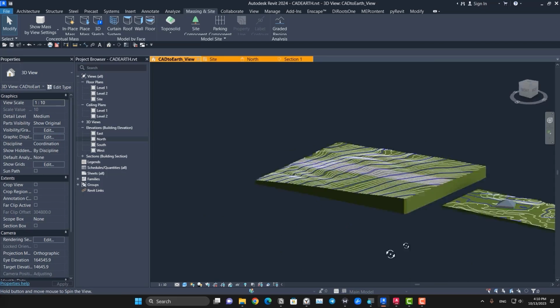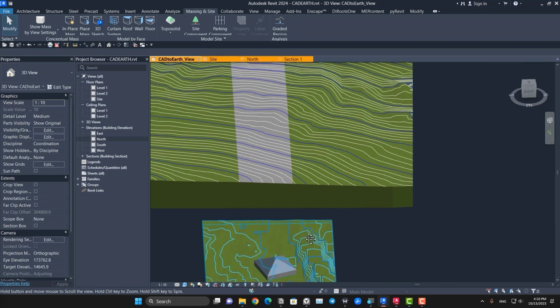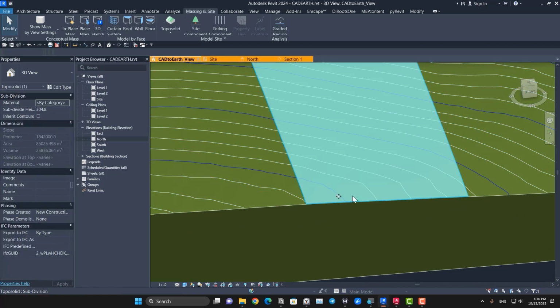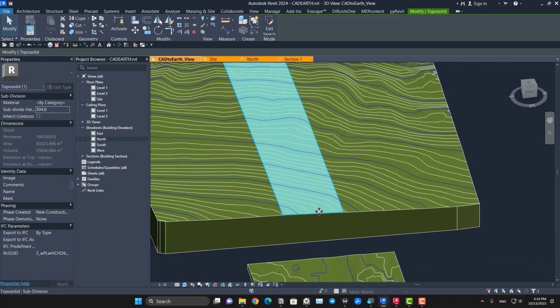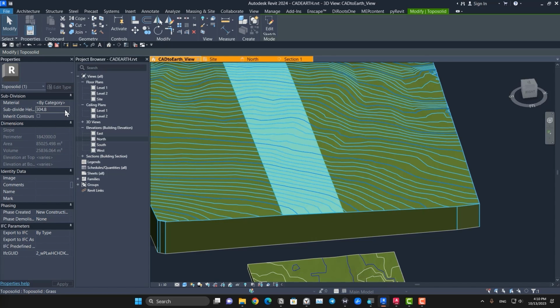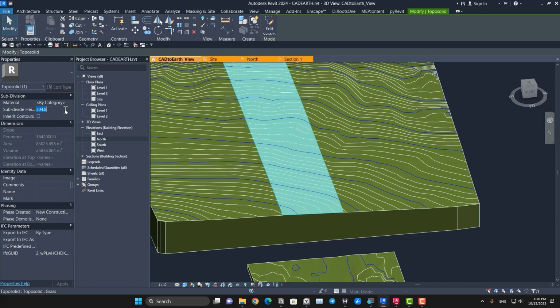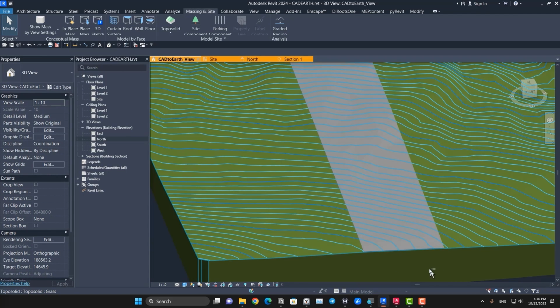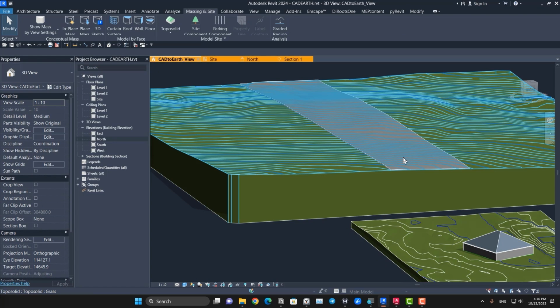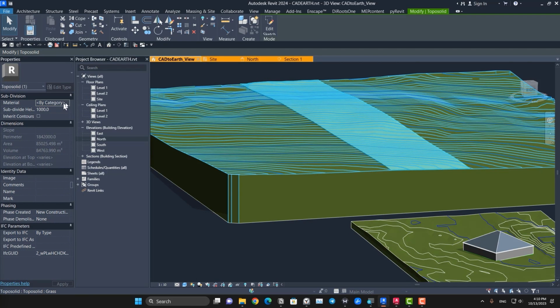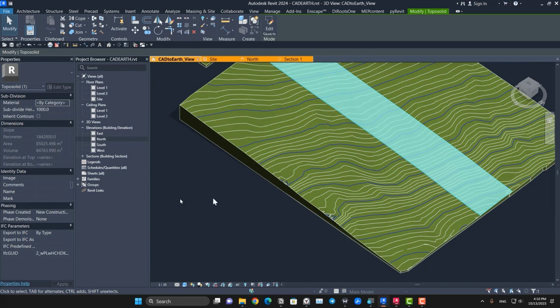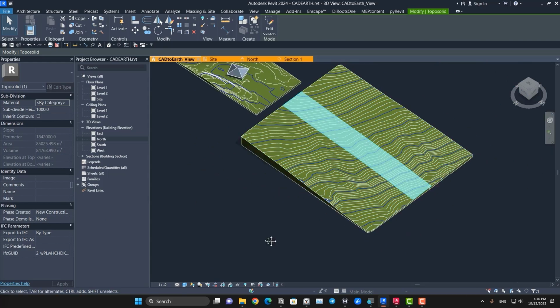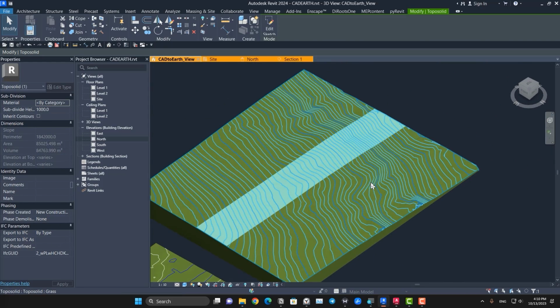There are some reasons that I don't like to use this subdivide for my roads and those things, because the first one is that it doesn't have the minus option, so you can't go into the topography. You just need to have an additional height. For example, let's put it on 1000. Now you can see it just comes up and it doesn't have anything else. You can change the material and those things, but it's not that effective. It's just good for changing some materials in different areas. But I will show you another way to create roads and curves for it.